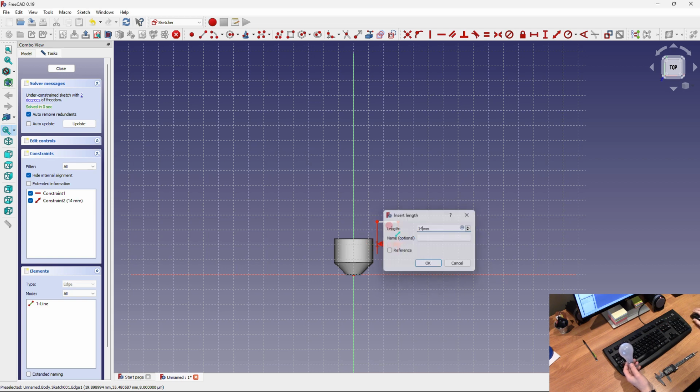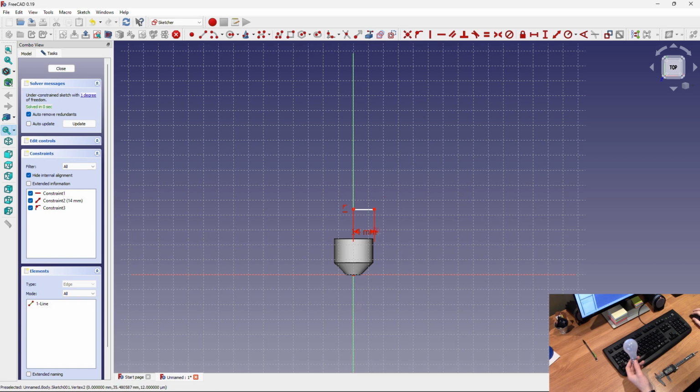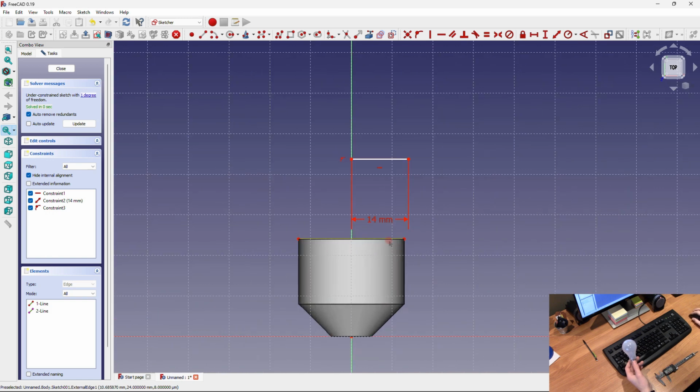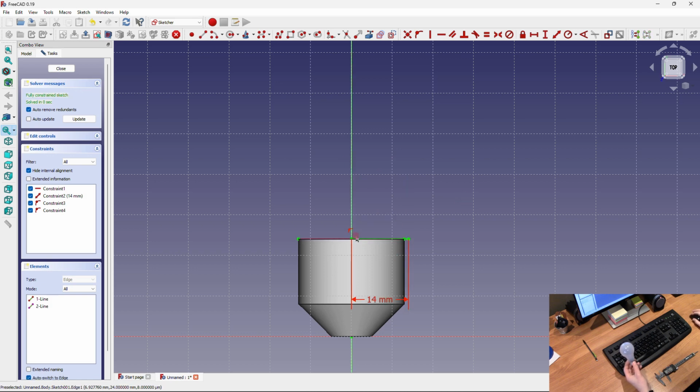So right now we have this line, and we need to constrain it to our axis, and then we're going to have to constrain it right here. But in order to do that, select this blue box up here and make this edge constrainable. So now you can see these 2 points, and there is also a line connecting them. So let's use our point to line constraint tool and constrain that. You'll see that this sticks out a little bit, just like the light bulb.